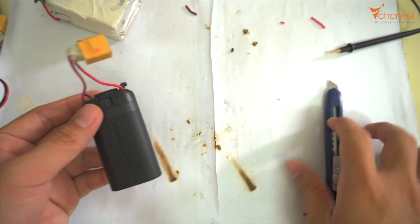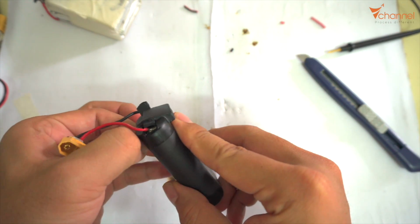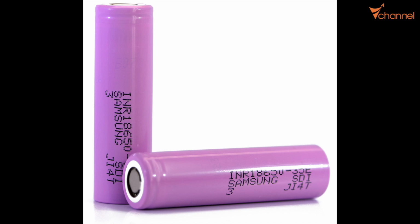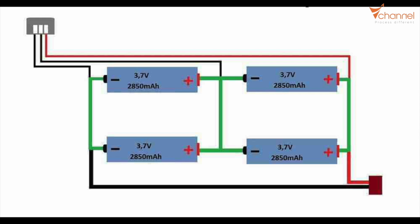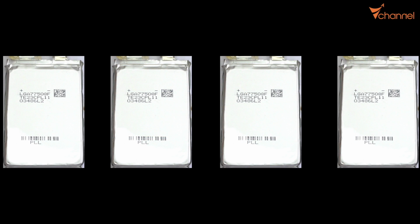Now the next method is to replace the battery cell. I will remove the old cell completely to replace it with a higher capacity cell. That's a pink cell, 3300 mAh, and I will replace it with 4 lithium polymer cells, 3830 mAh each cell. For the battery, I will connect 2S, 2P, that means 2 serial and 2 parallel. So we have a total capacity of up to 7,660 mAh.